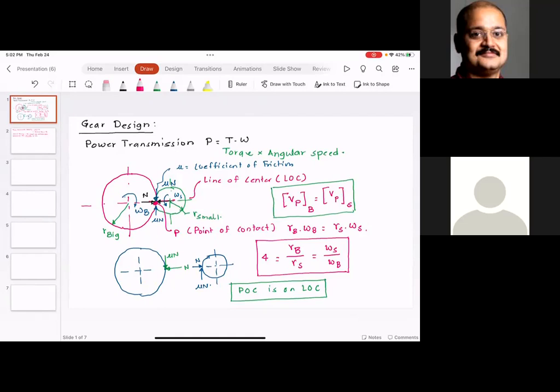What are the disadvantages of chain drive? The problem with chain drives is even though they are positive transmission elements, they are not as forgiving as belt drives. Which means you have to have accurate center distance. You cannot have sprockets out of alignment. If you have a minor misalignment between the sprockets, after some time, the chain would just fly off.